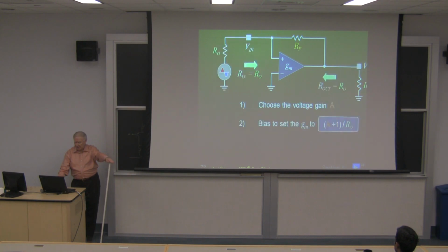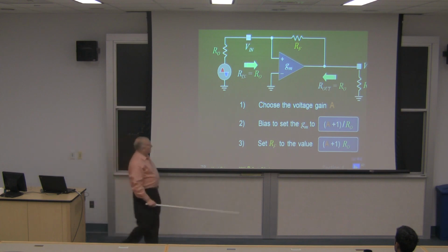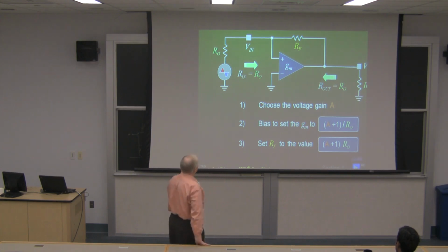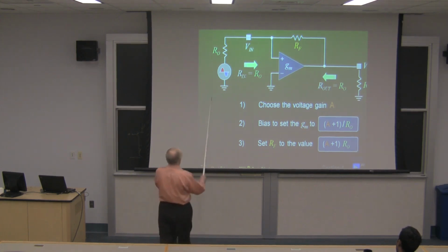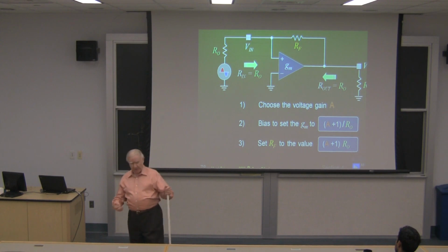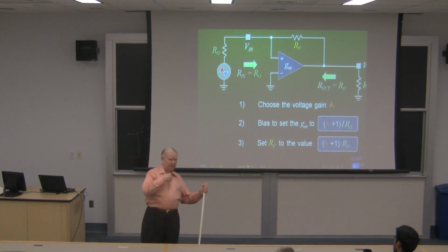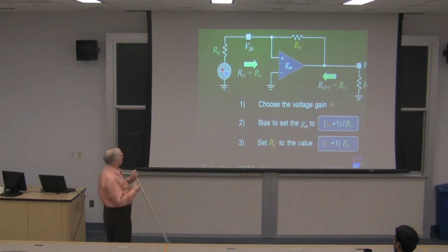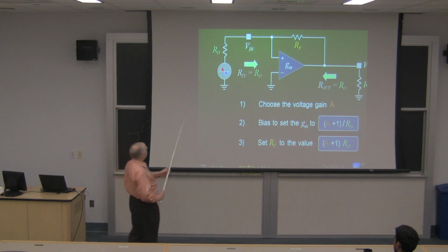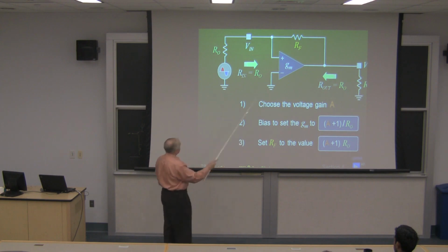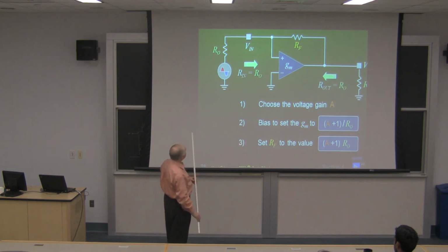Forgive me for being quick. Here it is. It's so easy to get this right. If you have a GM device, let's just say it's a grounded source transistor, I don't really care, and you wish to match a source resistance of R0, which, by the way, may not be an antenna. There are all kinds of signal sources. For example, in ultrasound, we're faced with the equivalent source resistance of a piezoelectric crystal array, which in itself is pretty complex. But generally speaking, people like to assume it has a nice simple number for an impedance. It's a bit of a mistake. They do that anyway. And so you want to match this, which may be 200 ohms, to an amplifier. So it's not just RF in the ordinary or wireless sense.